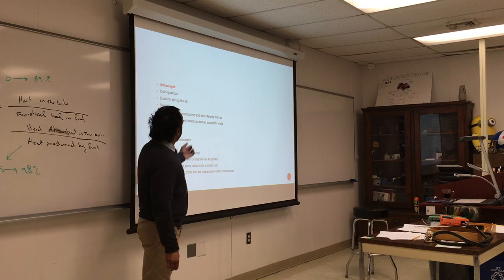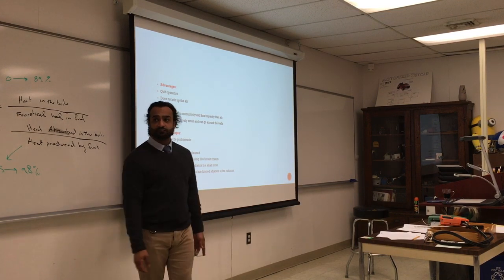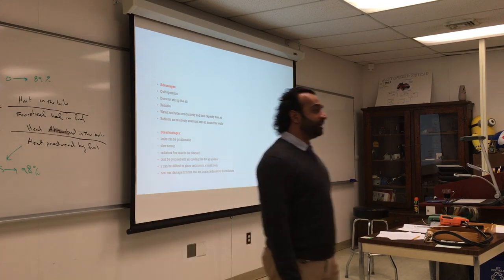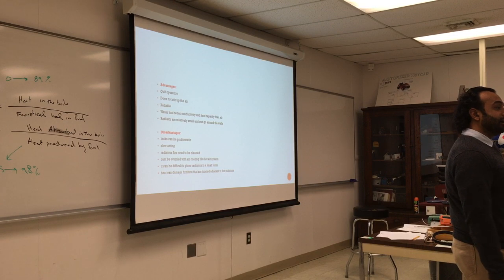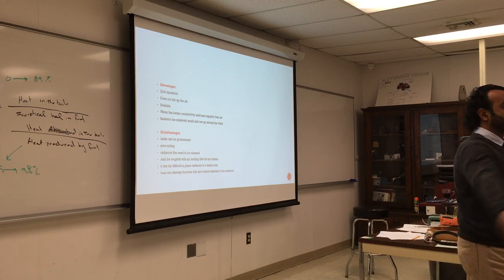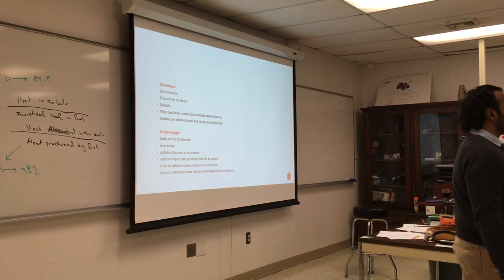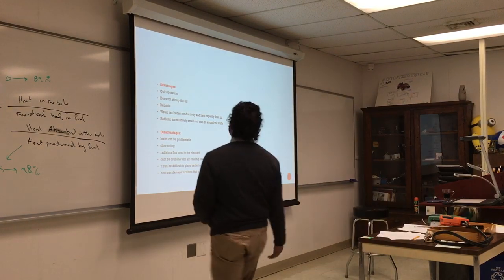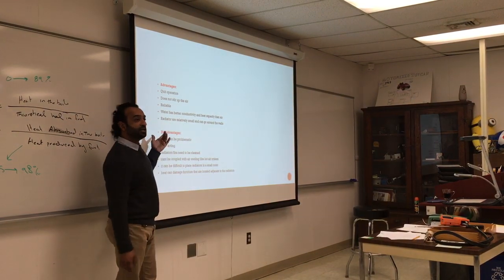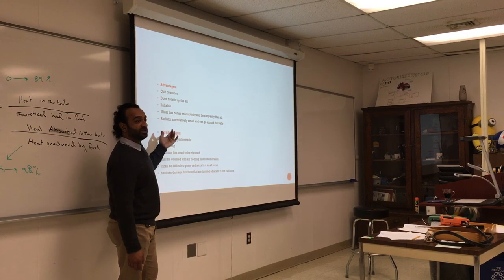Radiators are relatively small and can go around the walls. Again, that also can be an issue because if you put furniture that blocks the radiator, you have lessened the productivity of those radiators. And if you have a big room like this one, and you want to use baseboard radiators, I'm going to go around the room probably twice to get the heat I require. So it could be an advantage and a disadvantage.